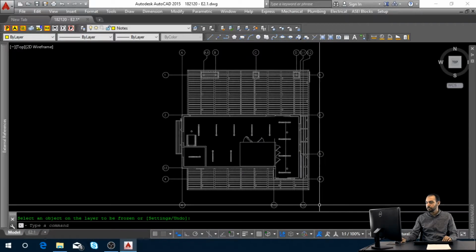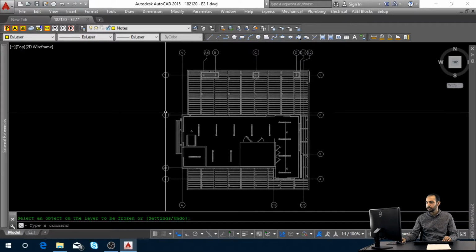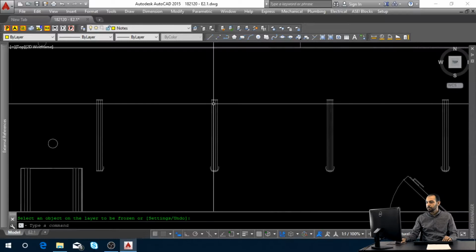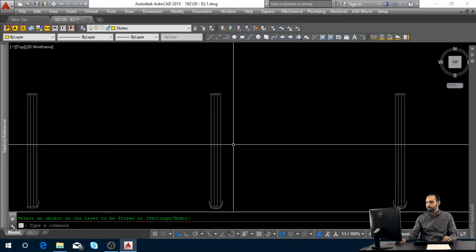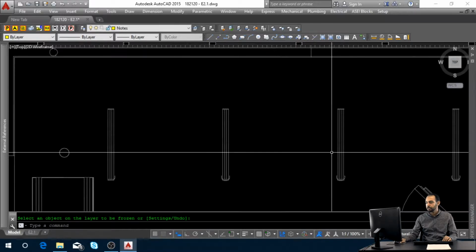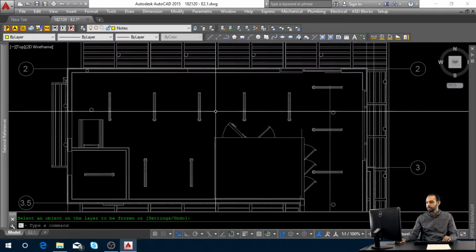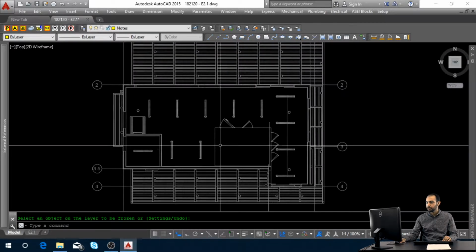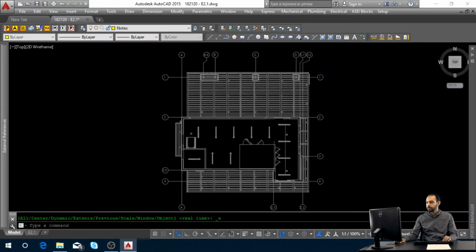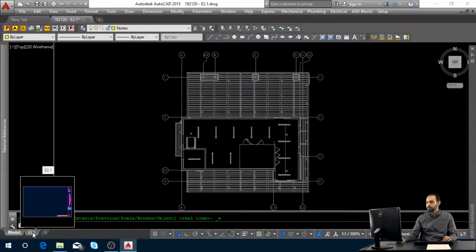And so you should be left with, these are our tags, our section tags. You want to leave those there. And these are our light fixtures here. So we're going to be leaving the light fixtures for now. And here the architect has located where they would like them to go. And we can place our light fixtures above this when it comes to it. But for now, we're going to leave it like this. So this is our RCP. And we're going to go to our paper space.